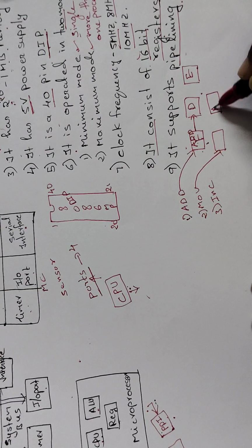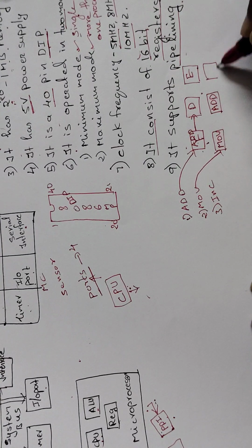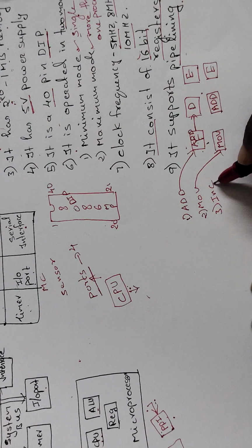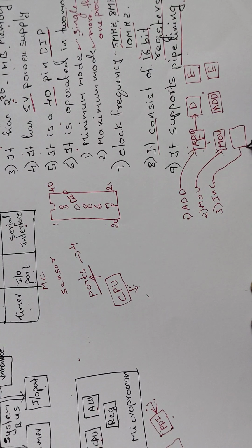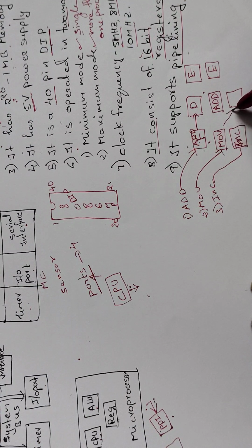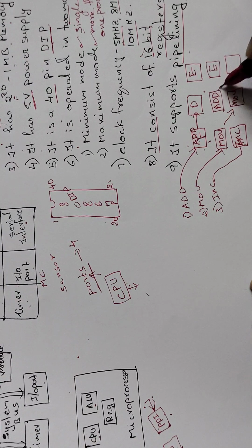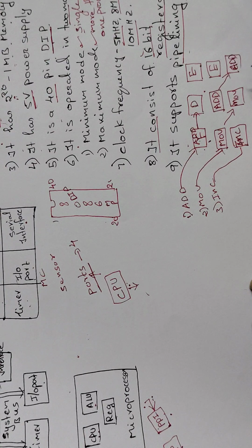After fetching, the add instruction is sent to decode, and the move instruction is fetched. Next comes execute. For the next step, inc is fetched, the move instruction moves to decode, and the add instruction is executed.